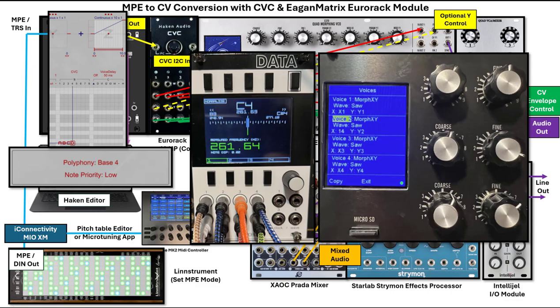One thing we're going to want to make sure is, if you have oscillators connected to this setup, go in and, using the scope or however you can, fine tune the oscillators so they are as close to the played pitch on your instrument, be it the Osmos or instrument or whatever, as you can get, because we're going to be using micro-tuned offsets here, and if you're not dead nuts tuned to your frequencies, you may get unexpected output.